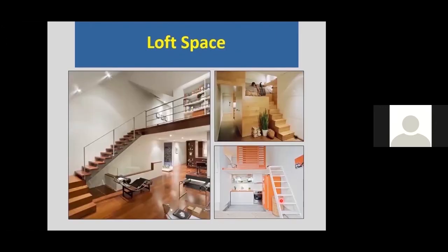You can have a loft space in these units. So a loft would be open to the surrounding space and no more than 33 1/3% of the space below. So what we cannot have located on this loft is any feature that's required to be on an accessible route within a single level unit.